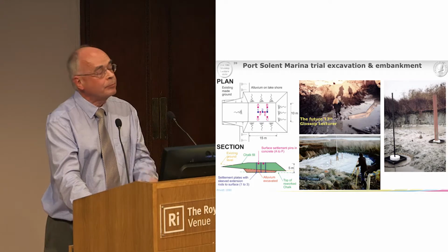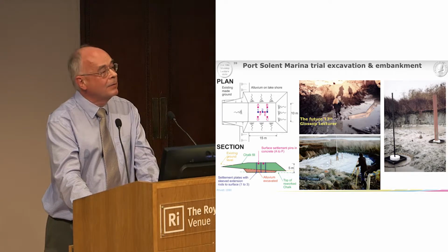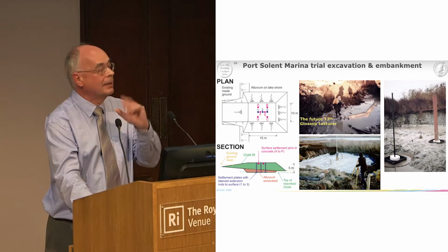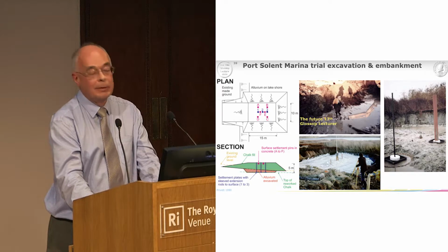And when we got to the top, we set a number of surface settlement pins into concrete, so we could measure the top and measure the bottom, and then by difference we could measure any internal settlement of the fill material.